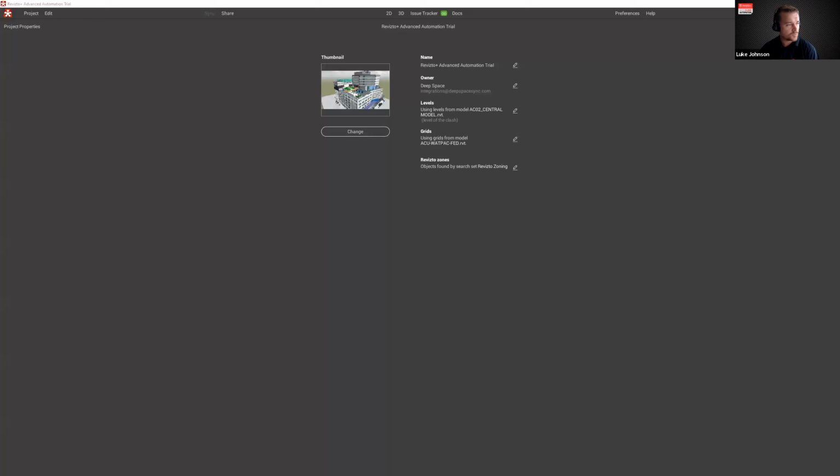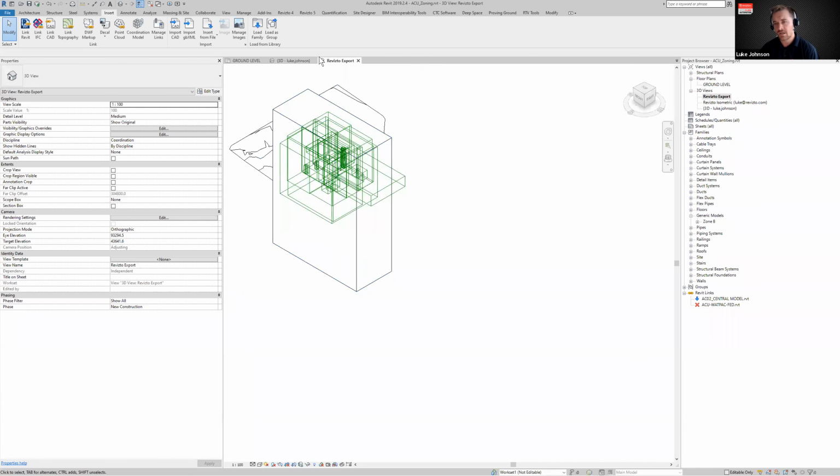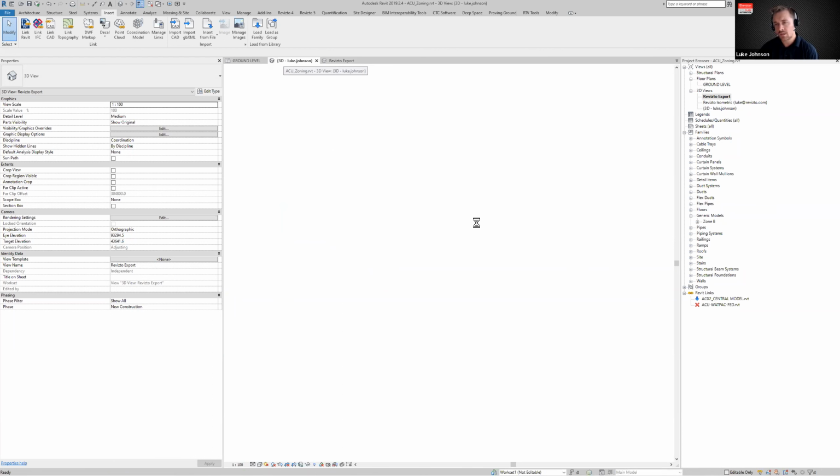Well, you do have to do a little bit of modeling work. And I'll just show you a quick example in Revit here. What we've got here in the background is a Revit model, which we've only got the architecture model linked in. And what we wanted to do is break it into two main construction zones because there was kind of an existing zone and a kind of proposed area, right? Kind of zone A, zone B.